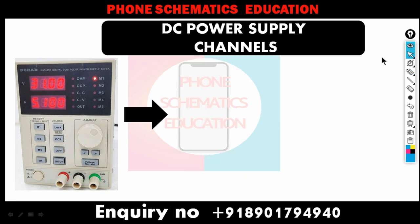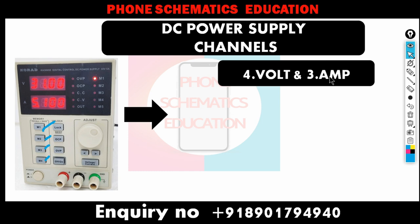Now next, the DC power supply channels. These are the channels M1, M2, M3, M4. There are four channels in this DC power supply. I'm using this one. Whatever channel settings I'm applying in my DC, I will share with you. First, 4 volt 3 amp in M1. I'm using this one for turning on the phone. Whenever a phone comes to me, I test and diagnose with this through a boot cable or BMC circuit, whatever I have.